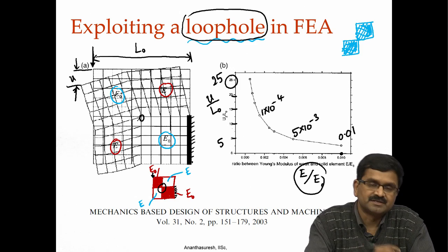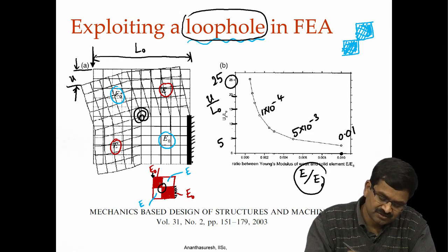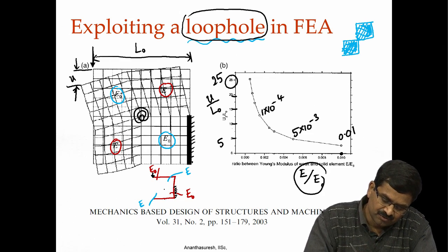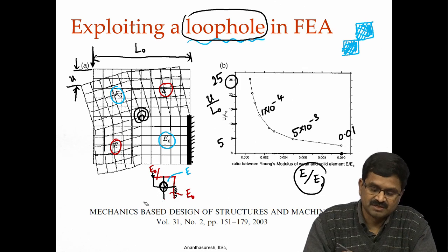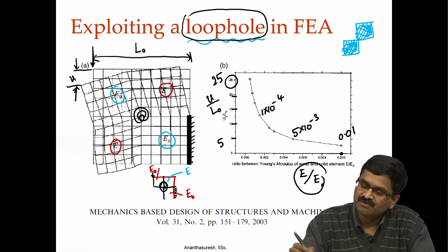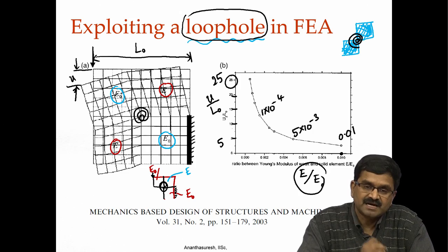So, we have a hinge here, and that hinge now has a torsion spring. We can think that this hinge is not simply a hinge between two things, we actually have a torsion spring. So, that is like an elastic pair. Here we have a hinge and a torsional spring between the two things, and that is exactly what finite element analysis is being exploited here in order to give us a design that has hinges.